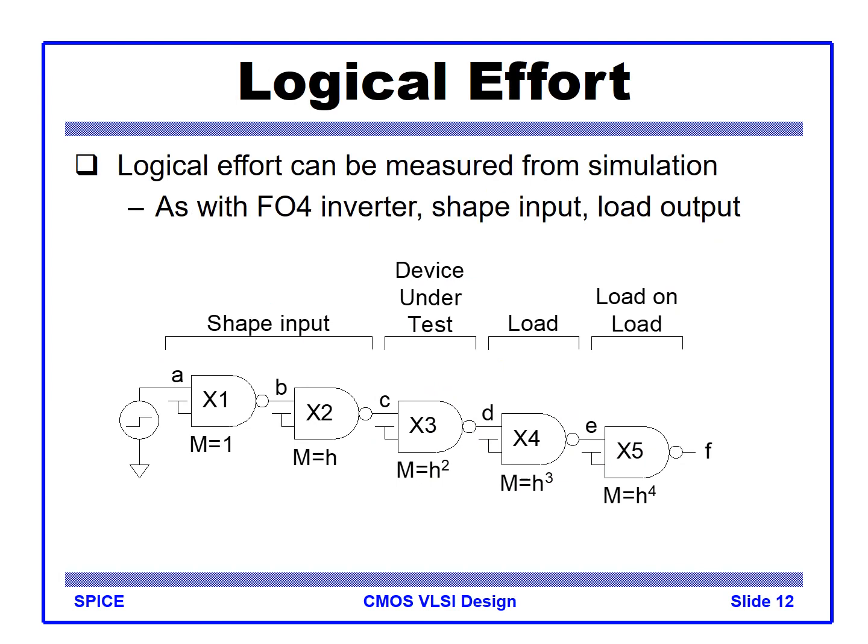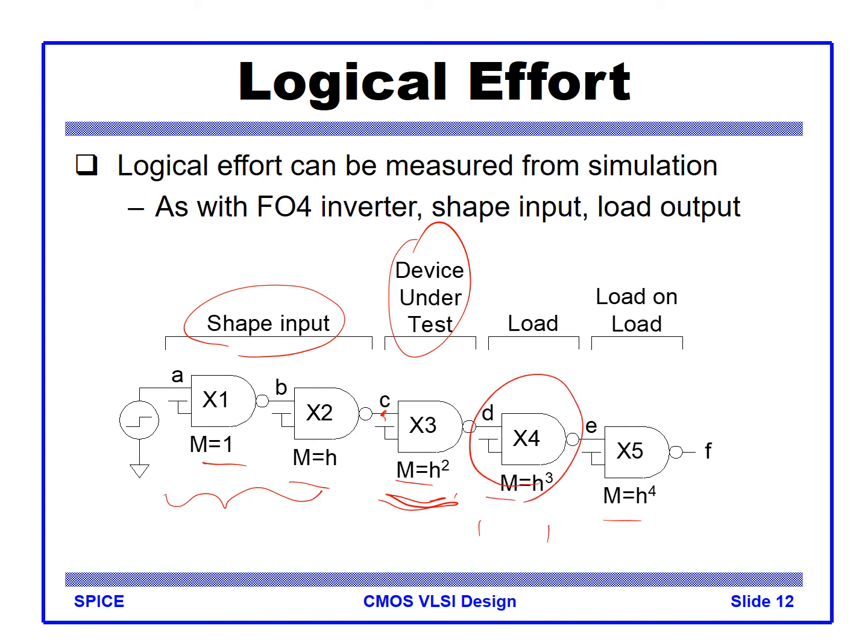So this is one setup that we can use to measure the logical effort. The third one is actually the device under test. As I mentioned, we put some additional input gates to shape the input properly, so the input rise time is properly settled there. Each stage has a fan out of H, so ideally, for a fan out of H, we get the same delay. And we also have a load setup, a fan out load of H.